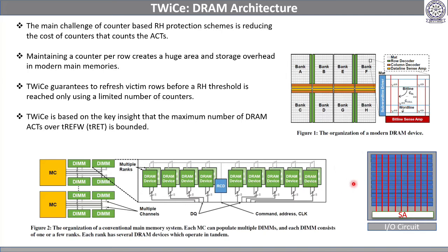This internal remapping is stored in a one time programmable memory inside the DRAM device. So the memory controller has no knowledge about it. This is the internal mapping, and it is a one time remapping done during the testing phase. So ultimately, when the memory controller sends an activation for row number 1, it knows that it is sending activation for row number 1, but this row number 1 is damaged, and during the testing phase, a spare row, the last row, is used instead. So the memory controller is sending activation to row number 1, but it is activating the last row.